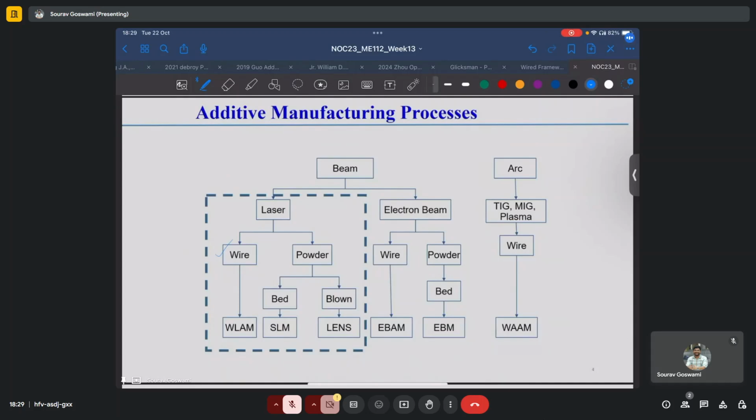Should a beam of electrons encounter other heavy particles such as inert gases in their path, they will simply scatter and they will not be able to reach the target surface. So we will not really be able to print anything.